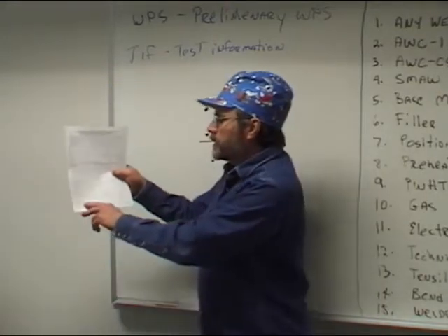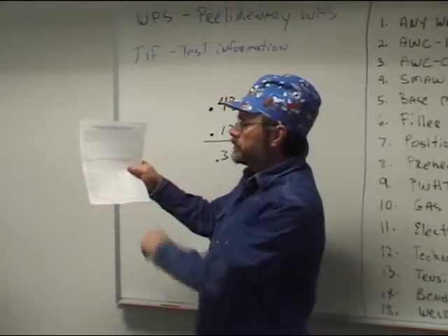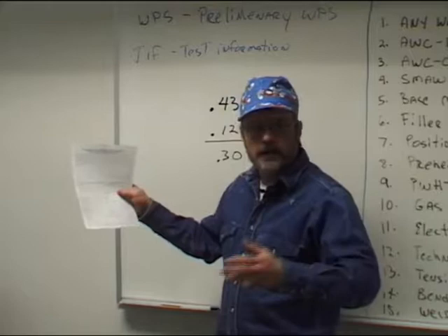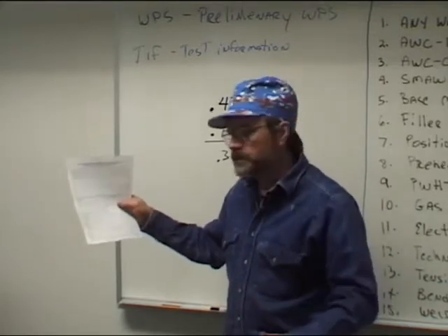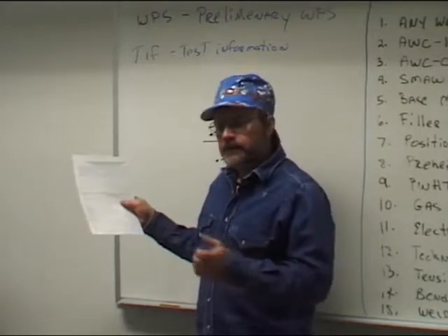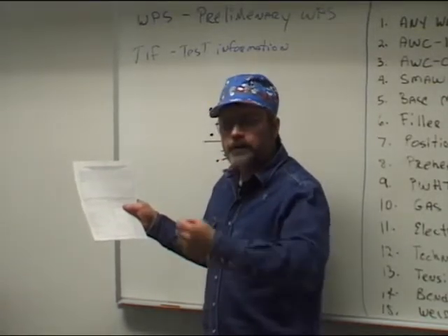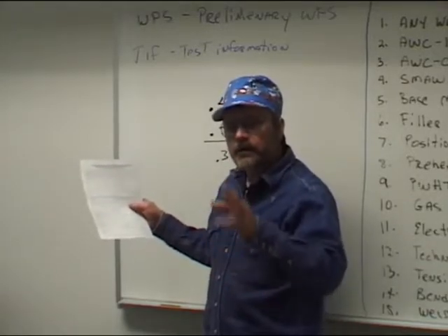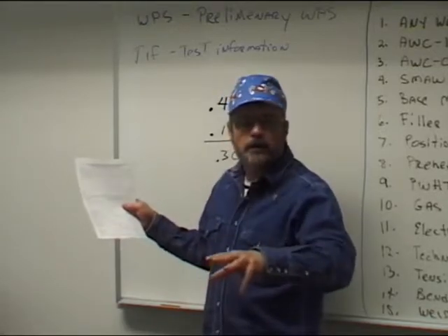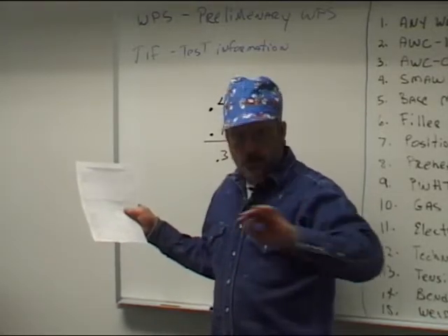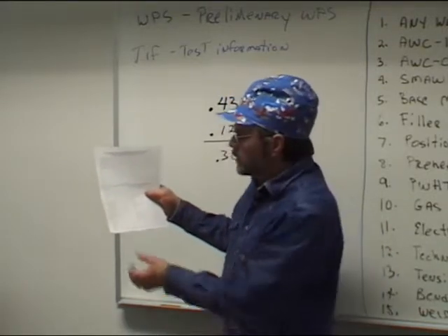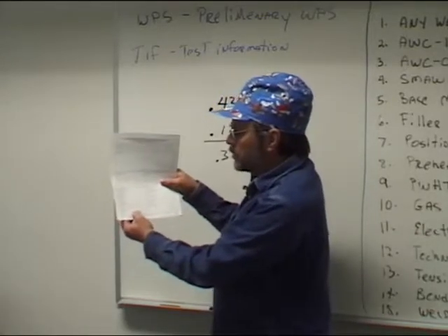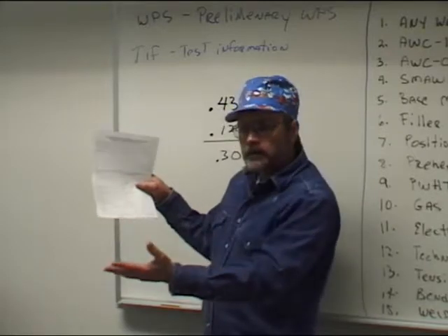Then we come to preheat, QW-406, preheat temperature. I usually like to make a welder drive the moisture out of the joint. They don't have to really raise it up to 200 degrees or anything like that. That's unnecessary. But pipe sweats, and if you take a torch and you sweep it across the material, you'll see that it'll drive moisture away from the joint. I like to do that to help avoid any porosity in the weld and to drive that hydrogen away from the joint so we don't have any underbead cracking later on. So I would typically tell them, take it up to 75 degrees or take it up to 80 degrees, whatever, and you would write that in there if you had any, and if you did it.